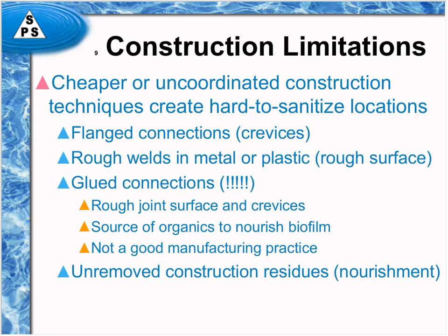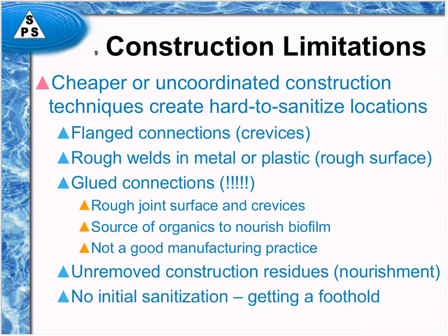Another situation that occurs is that sometimes these water systems are just put together and then, quote, flushed with water to clean them out, and then the hands are slapped together and whoever put it together leaves, and there are all manner of construction residues that remain on the inside of the pipe. PVC pipe sitting outside for some period of time collects all manner of dirt and dust and all kinds of debris inside. And so all of those residues associated with the piping, if they're not specifically cleaned out, will serve as food for the organisms to grow in.